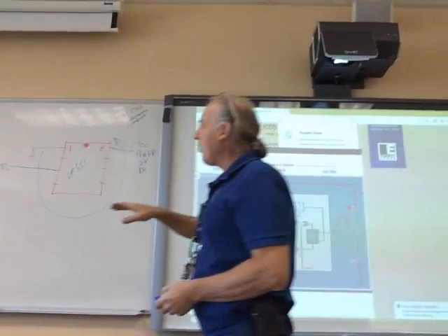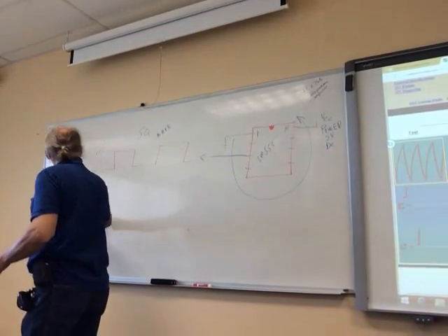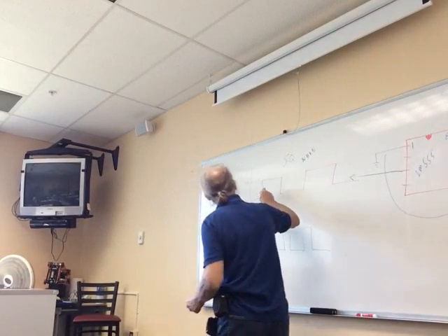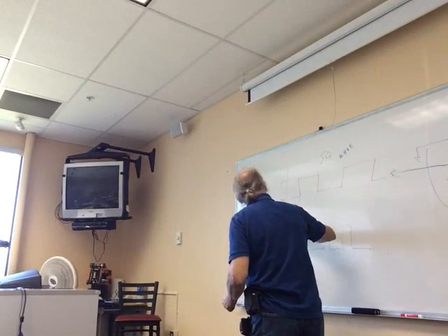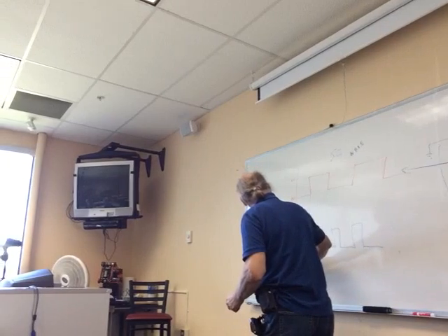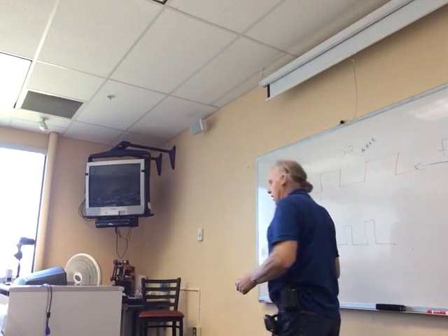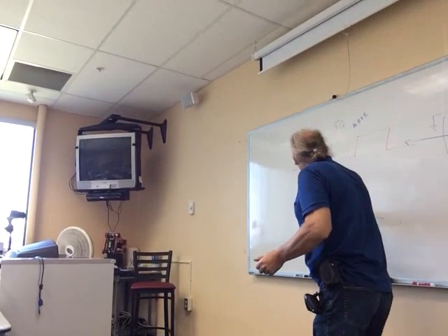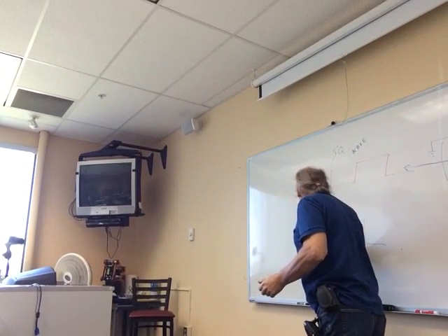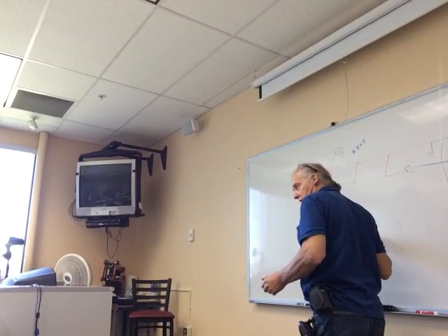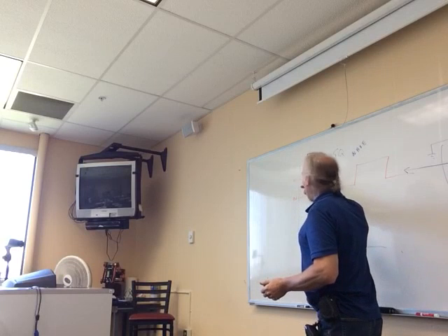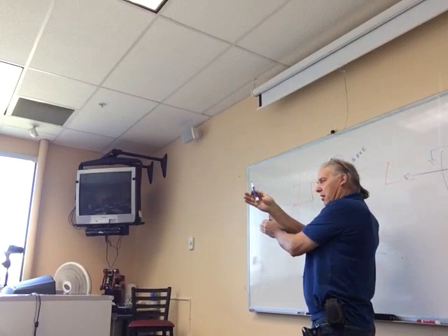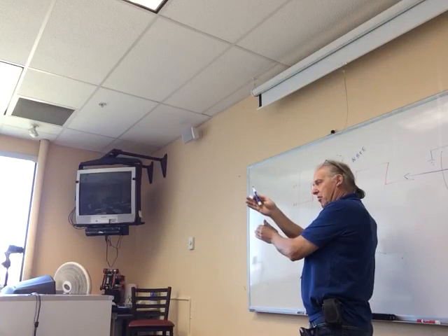Okay, so I might be looking at some kind of wave here that's doing its thing, and I want that to start right here, then I can use pin 4 to get that done. I can drive it with an inverter or something, and I can pulse it, and it will trigger on whatever my signal is. This is my signal. It will trigger right there and start so I can utilize my pulses, and they won't be out of whack, okay? They won't be out of faster or slower, okay? Does that make sense, Steve?